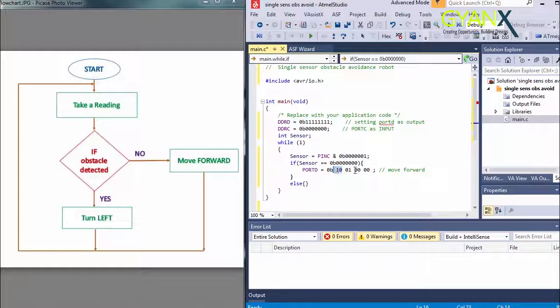If you have connected the motor wires as instructed in the assembling section, you have to send 1 0 to this pin of port D to move the left motor in anti-clockwise direction, and 0 1 to move the right motor in clockwise direction. So in order to move forward, you have to send 1001 and 4 times 0 to port D, then the robot will move forward.